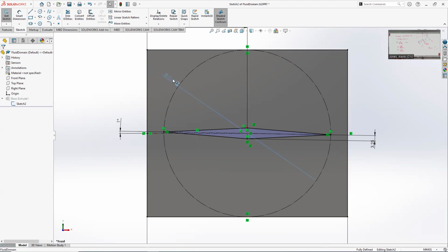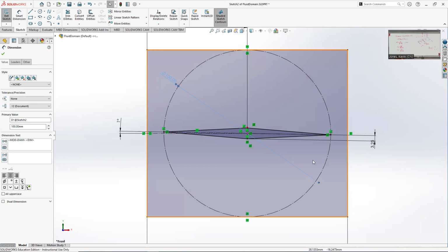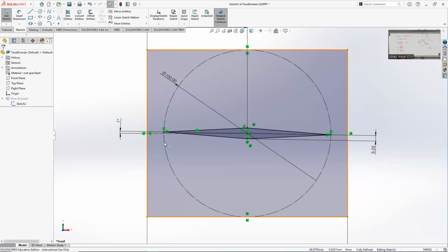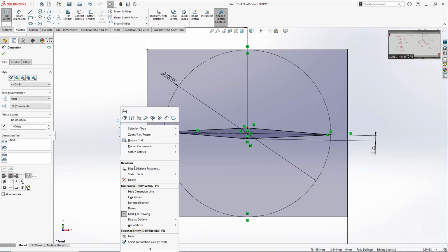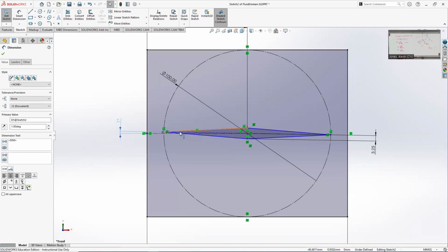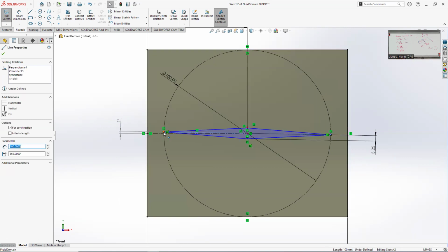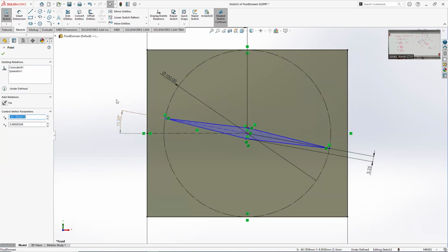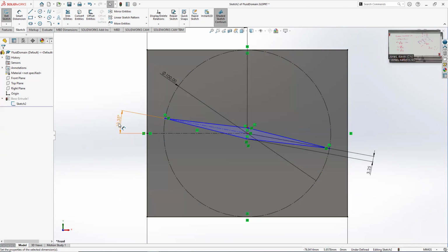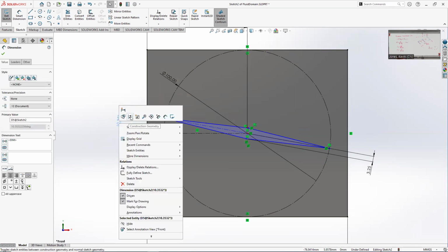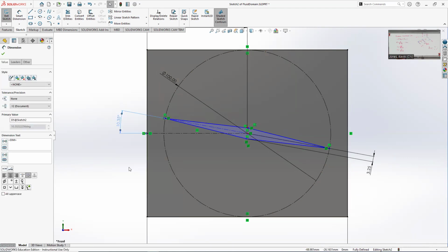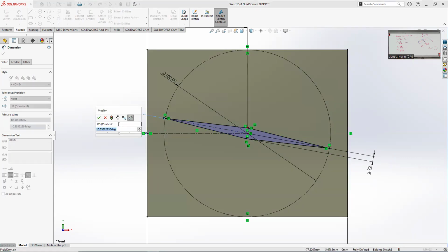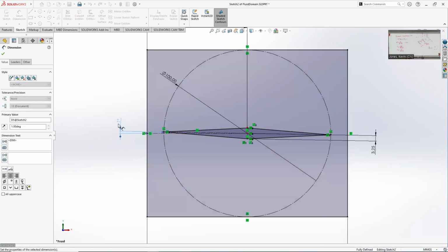We got a chord length of 100 millimeters, half thickness of 3.25 millimeters. And the way I generated this, I attached the airfoil to a chord line, which I can move to any angle I want. If I type something in, in degrees, I get whatever I want.